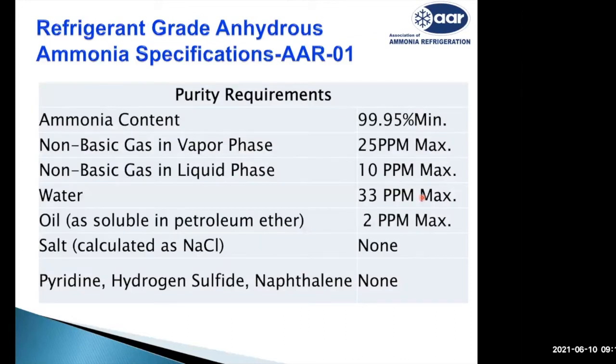Second important parameter is, of course, purity of ammonia. As it has been explained to you all the last 2 days, all refrigeration systems, whether ammonia based, any synthetic gas based, or any natural gas refrigerant, work on the pressure temperature characteristics of a refrigerant. And those characteristics are dependent on the purity of the refrigerant. In case of synthetic refrigerants, they depend on the mixtures of refrigerants used to create them, and the accuracy of those mixtures, whereas in case of ammonia, it's the purity.